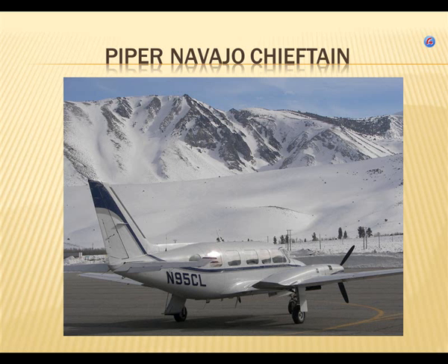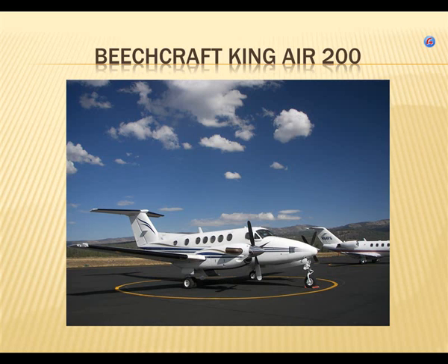So you need to know the difference between the vertical stabilizer, which is fixed to the body of the aircraft, and the rudder, which is also fixed, but it's movable. Here's another one. Here's a Beechcraft King Air 200. And you can see in the back the difference between the fixed portion, which is ahead of the tail, in the back, the rudder. So all of this, including the vertical stabilizer, the rudder, and the horizontal stabilizer, and the elevator, are all part of empennage, tail feathers.